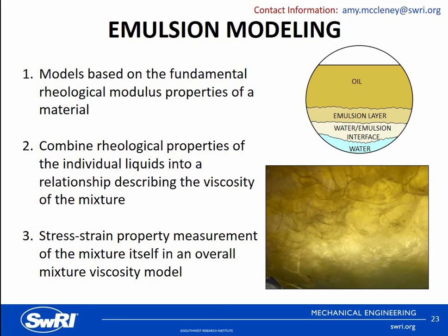Crude oil and water emulsions are viscoelastic fluids that have a complex rheology, sometimes in which the viscosity of the emulsion is much higher than the oil itself. Some emulsions have very low solubility, where the solution mixture will form a thick film that surrounds the water droplets, kind of like the image that you are seeing on the screen here. This film inhibits droplets from contacting, thus preventing droplet coalescence, which prevents the separation of the two fluids into their respective bulk phases.